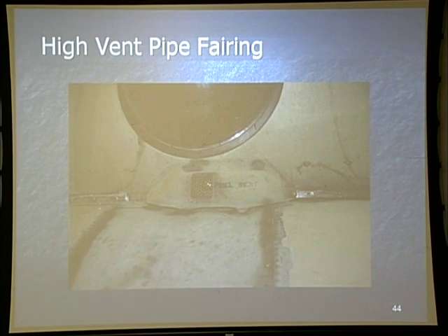Which is why it's important that you understand and recognize it as fast as possible. And you can see on page 14 of your handout, the high vent pipes also vent fuel in the event of fuel venting from the bottom. The pod exceeds 9 gallons per minute. It actually attaches a number to it. But that's the only time that becomes a factor. Any questions about that?